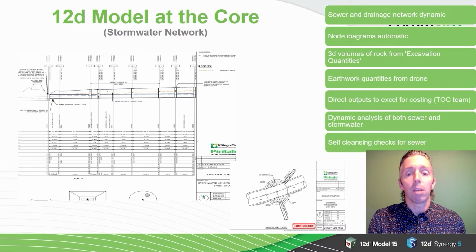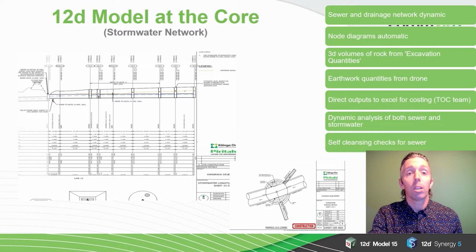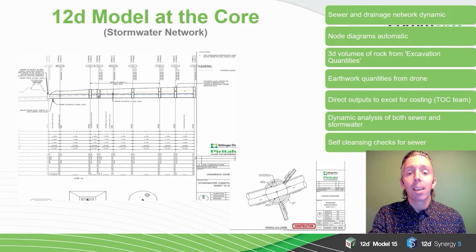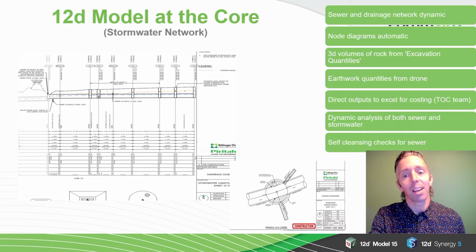We found the easiest way is to have one CAD file with multiple XREFs stacked on top of each other on different layers and then freeze off in the viewports, all inserted at 0,0. And then when we ran the 12D long sections, it didn't mess up the pagination if the length of the pipe changes. We have well over 20 pages of long sections per stage, so this is an important setup for us. The long sections are 95% complete from 12D. Sometimes we put in the odd dimension or label in CAD.